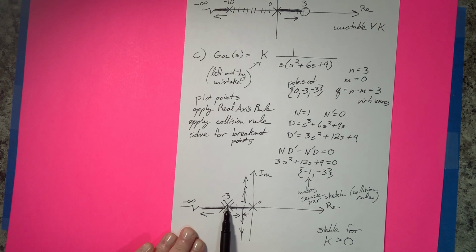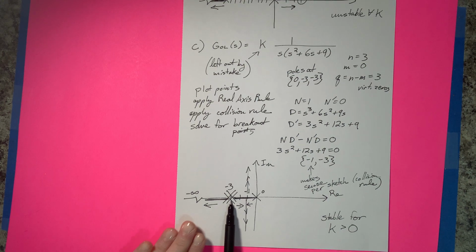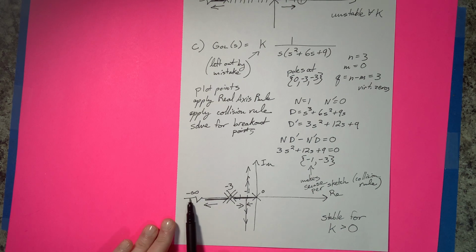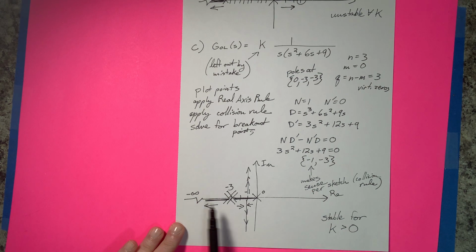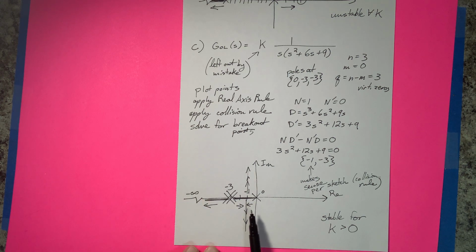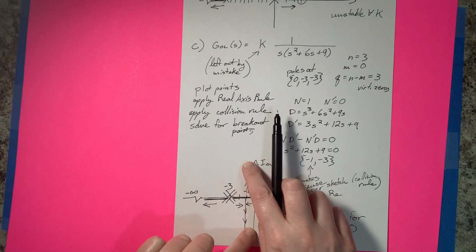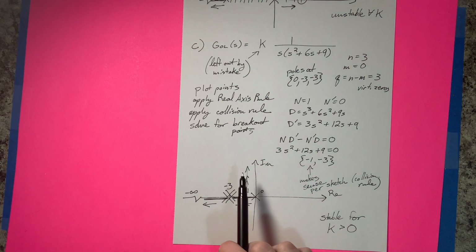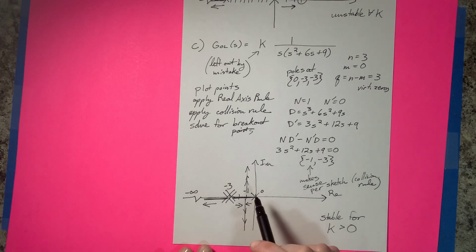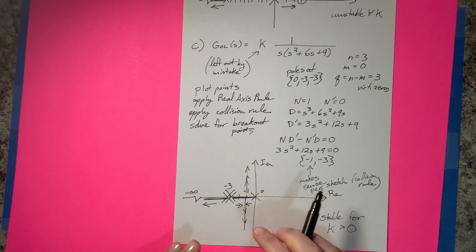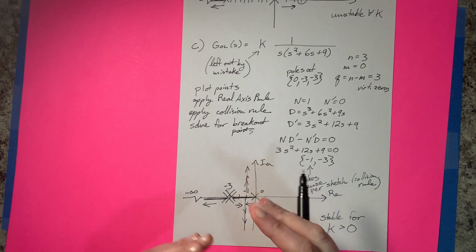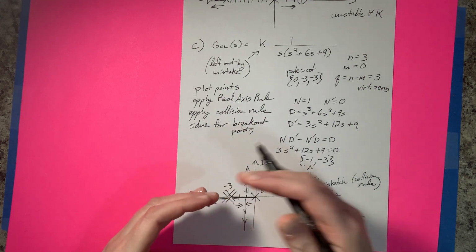As for the other pole at -3, it's going to move towards the virtual zero, so it keeps going out here. We do have 3 virtual zeros, keep in mind. One of them is going to be over here, and then the other 2 will be up and down in these directions. Now, we talked about before how this cuts the axis in a kind of even way, like you can think of a pie being cut into thirds.